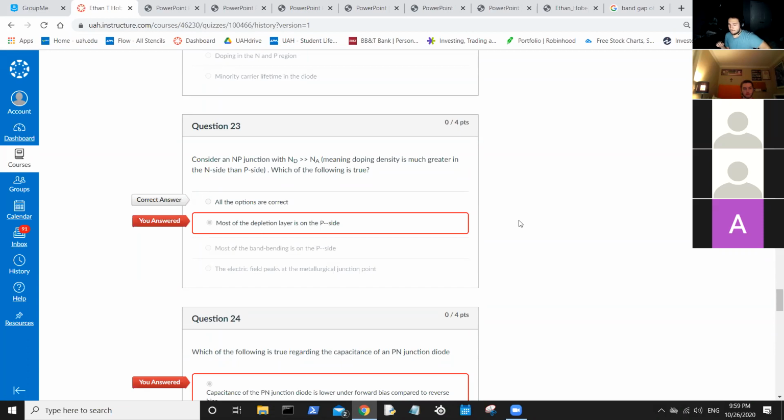Now, obviously, the general formula doesn't work for a PN junction because the material's resistivity changes based off of where you are positionally in the junction. So you can't just have a blanket resistivity for the whole thing, which is why you need to use different formulas depending on the case. We'll start with equilibrium.